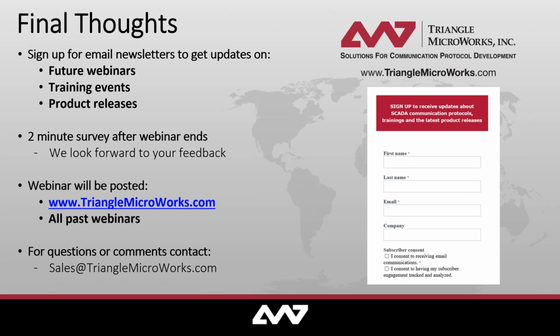Is it possible to create my own logical node or customize the existing ones in an SCL file? Yes, absolutely. But I would say context also matters there. If you're a device vendor, then that's a big part of your job when you're creating the ICD file for your device. As a vendor, you know the capabilities of a particular device that you're building, and you reflect or model those capabilities in an SCL file, typically an ICD.